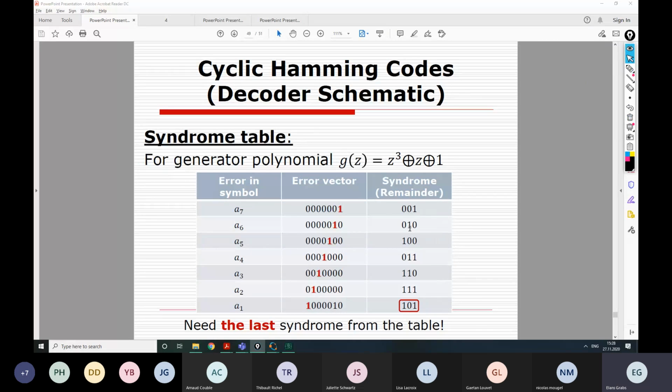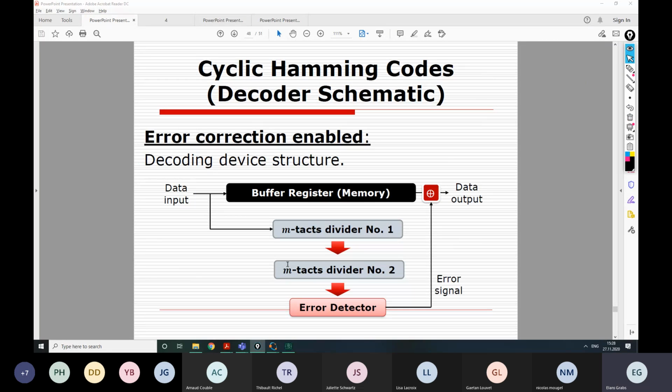So that's why we need the second schematic, because the first schematic will be busy processing the next code word that comes after our code. You must realize that this is an uninterrupted process. So we have received a code word, this schematic calculated the remainder, gave the result to this one, and it's already time to start processing the next code word by this schematic.